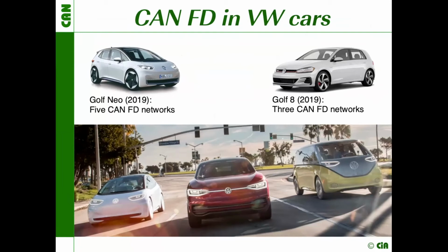CAN FD is nothing from the future. CAN FD is available today. The controllers, the transceivers, hardware on different levels, and it is even available in a system. Volkswagen, all the cars sold these days by Volkswagen, or the new all-electric ID.3 has CAN FD inside. Also, the Golf 8 has CAN FD inside.